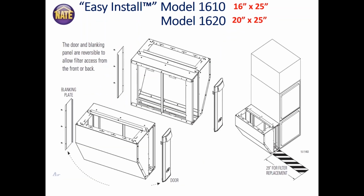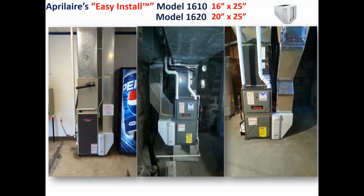There are tabs across the top perimeter that you can bend up or leave down to change the size of the return opening. You can also swap the door with a blank off plate, so you can have the door in the front or the back, which gives you a left or right return. Here are some pictures showing minimal modification to the return drop to accommodate a much wider filter because of that incorporated boot in the design.